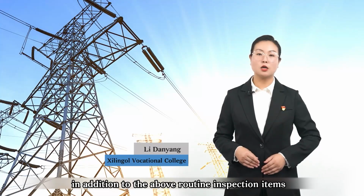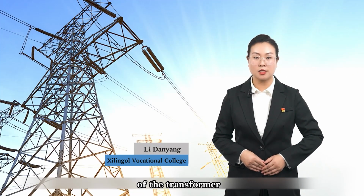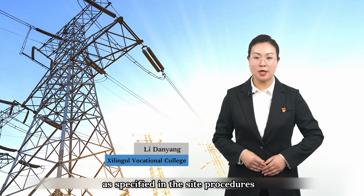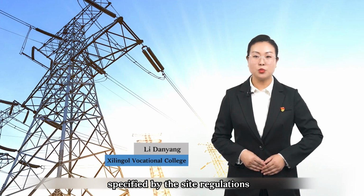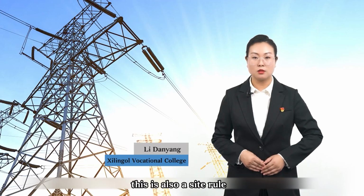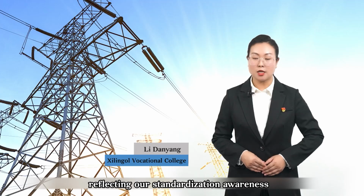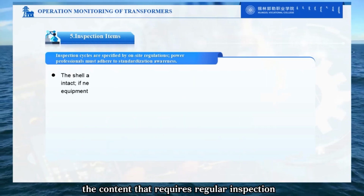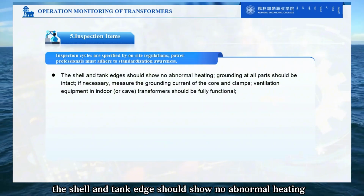In addition to the above routine inspection items, regular inspections shall also be conducted based on the structural characteristics of the transformer as specified in the site procedures. Other items and inspection cycles should be specified by the site regulations. This is also a site rule that power personnel must abide by, reflecting our standardization awareness. The content that requires regular inspection mainly includes the shell and tank edge should show no abnormal heating.